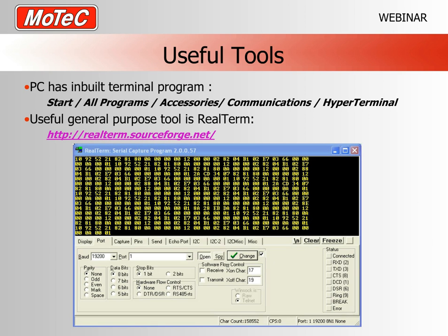Now, you should recall that most RS232 systems only allow a single receive device, especially within the PC domain, and therefore if you're running, for example, this RealTerm program, you can't open our telemetry monitor and access the same port.